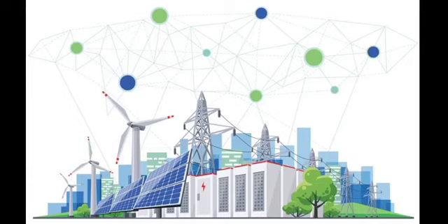Active power filters. These filters dynamically monitor the electrical network for harmonic distortion and actively inject counteracting currents to cancel out the harmonics, ensuring cleaner power supply. Power factor correction equipment. Power factor correction devices optimize the power factor of electrical systems, reducing reactive power demand and improving overall system efficiency. Isolation transformers. Isolation transformers provide electrical isolation between the input and output, protecting sensitive equipment from voltage spikes and ground loops.